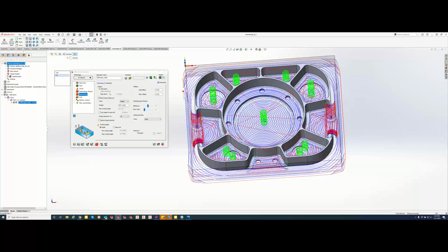One thing to remember is when you're using 3D iMachining, this is a roughing strategy. With that roughing strategy, we're always leaving material on the wall. Now, like I said, if you guys have a pretty wide open tolerance in there, we can put these at 0 for a wall offset and a floor offset, and we can get up to size. But like I said, it's all dependent on your tolerances there and your machine rigidity there. So you can do a rough, and I'm not going to even call it a finish, but you can rough it down to size.